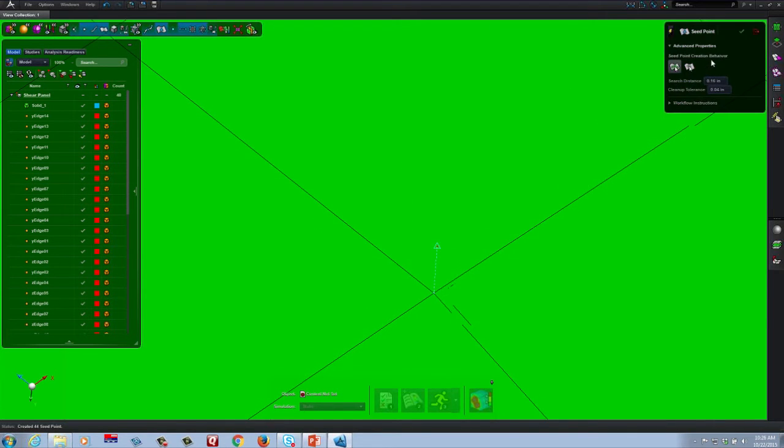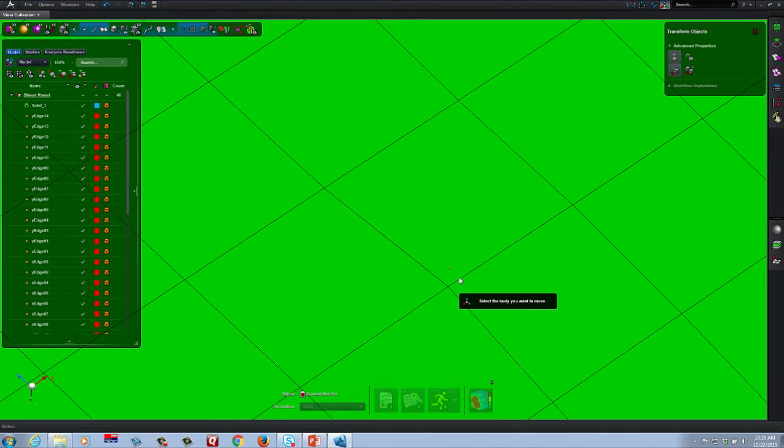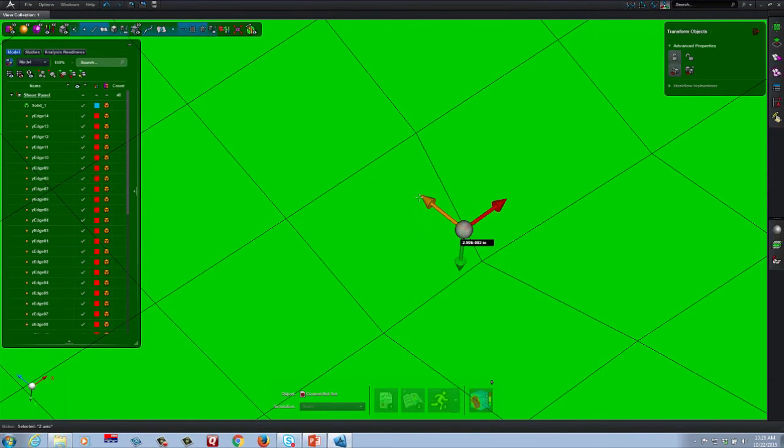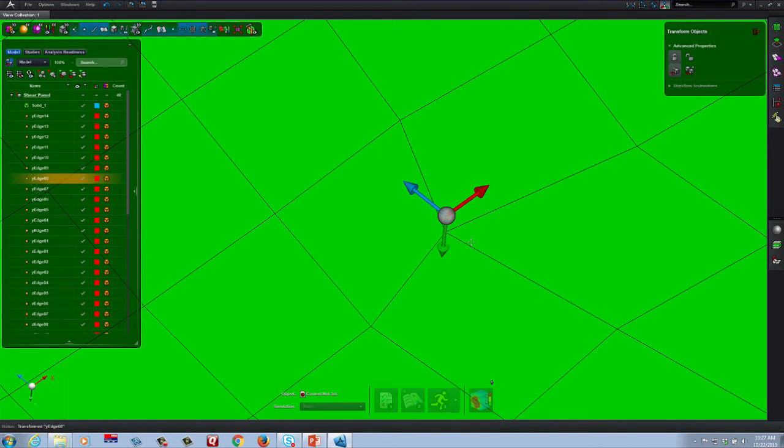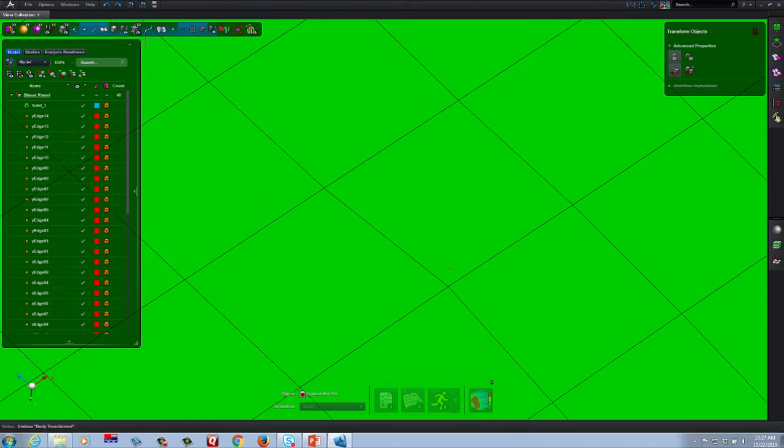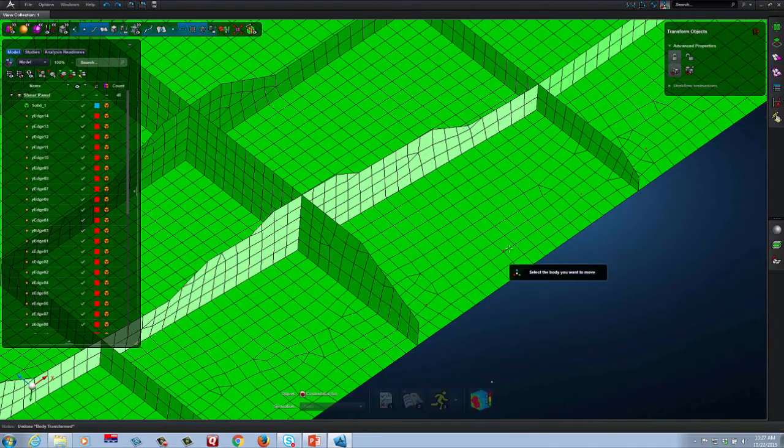We know that change is the ever-present constant, so a really cool capability here is I can come in and start moving this point around. And as I move that point around, engineers always do what-if analyses. We're always trying to make things better and improve things. Maybe we might believe we could improve it by moving the fastener location. So it's very easy to do that in MSC Apex thanks to the generative nature of the product. I'm going to undo that.